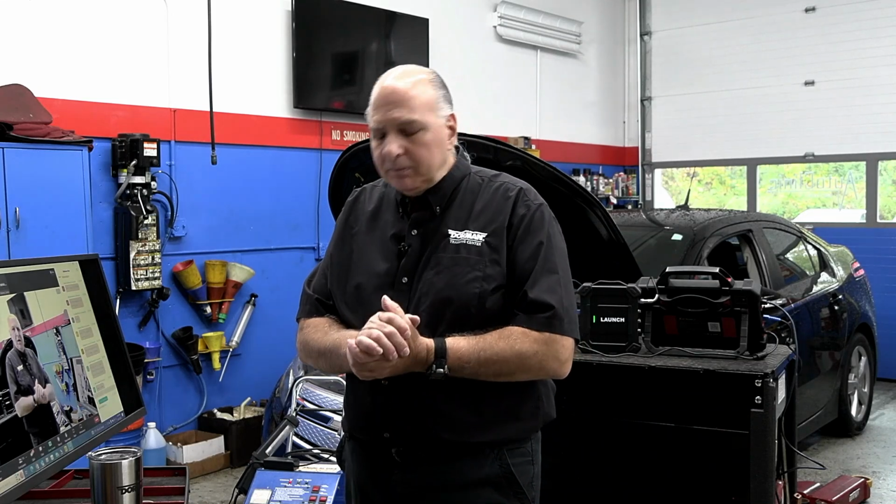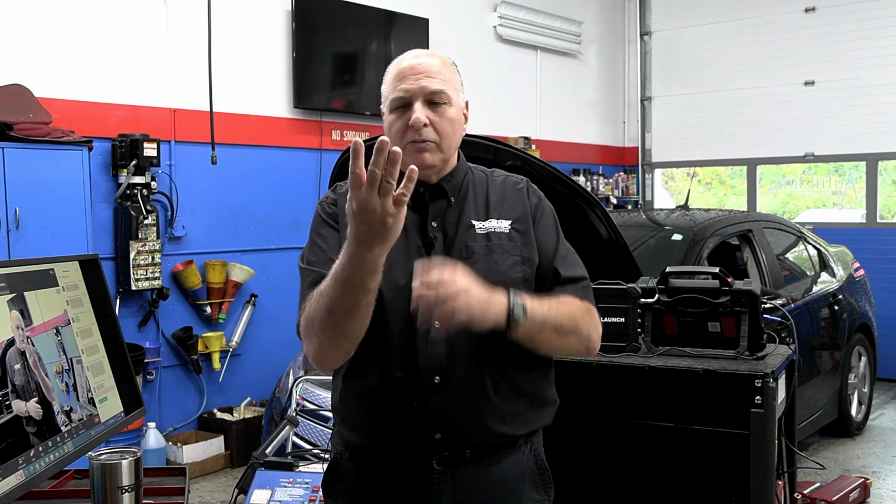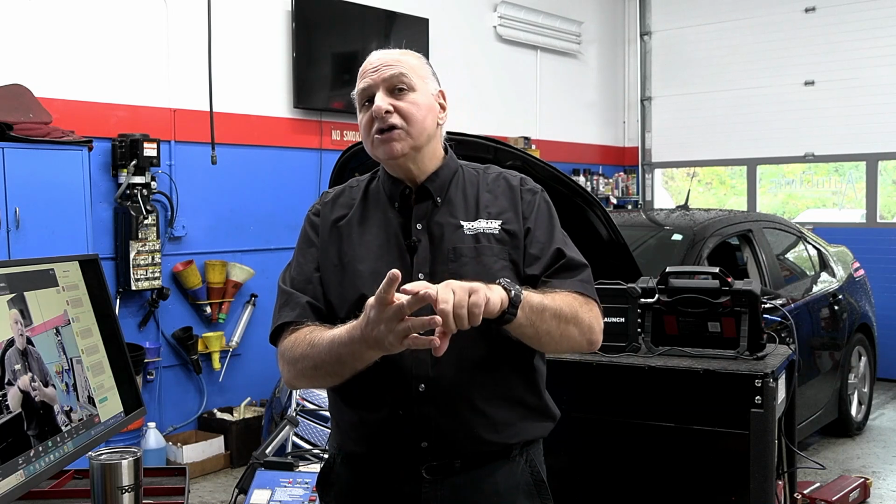Give you another example. Have you worked on Chrysler products? Go to the oxygen sensor wire, back probe it, and if you're on chassis ground, you're going to read 2.5 to 3.5 volts. And you're going to go, what the hell is wrong with that? Now remember, that's a four-wire connector. We've got a ground for the heater, a 12 volt for the heater, a signal ground, pin 5, right?